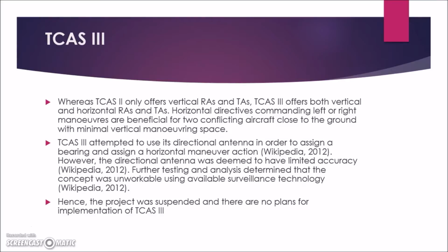For TCAS 3, it offers both vertical and horizontal RA and TA. Horizontal directive commands, left or right, are beneficial for two conflicting aircraft close to the ground with minimal vertical space.